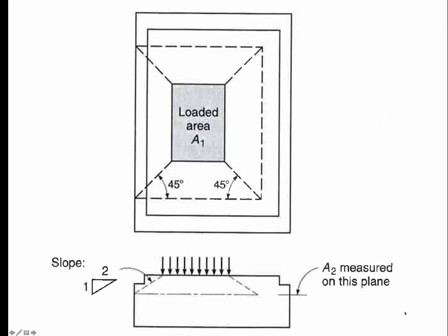This is the frustum shape. So this is now checking the bearing of the column onto the footing. Is there going to be a localized little punch out going on? What we have to do here is identify this 2-to-1, or 1-to-2 as it might be called using the geotech terminology, to be consistent with what we spoke of earlier in the class. Because, by the way, this is different than what we assume is going on in soils with that 2-to-1 method.